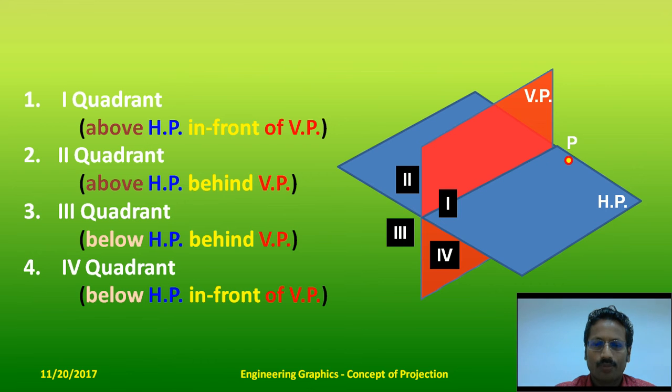Now, these horizontal plane and vertical plane are the two principal planes relative to which the object position can be specified, and of course the observer's position can also be specified with respect to these. In case of perspective projection, the relative position of the object and observer needs to be specified with respect to the plane of projection.